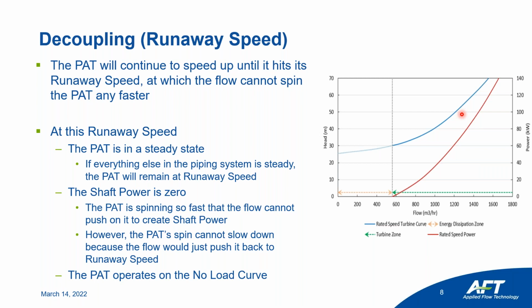So the PAT will continue to speed up in this free spinning state until it hits a runaway speed. At that runaway speed, the flow cannot spin the PAT any faster.